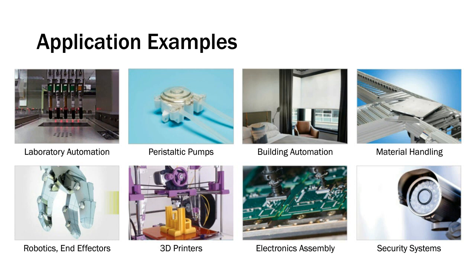So in those applications where temperature control is critical, rather than putting a chiller on the tubing or doing some other type of temperature control later downstream, just put a closed loop stepper on there, put a step servo motor on there, and the temperature issues go away.